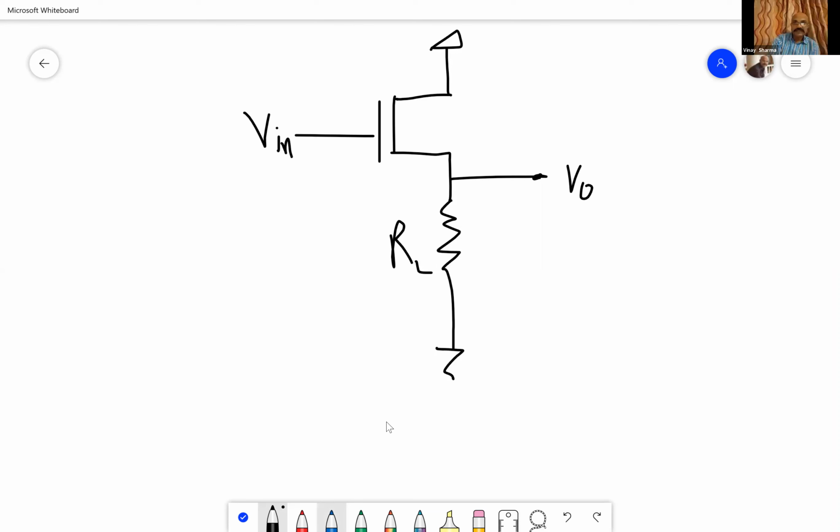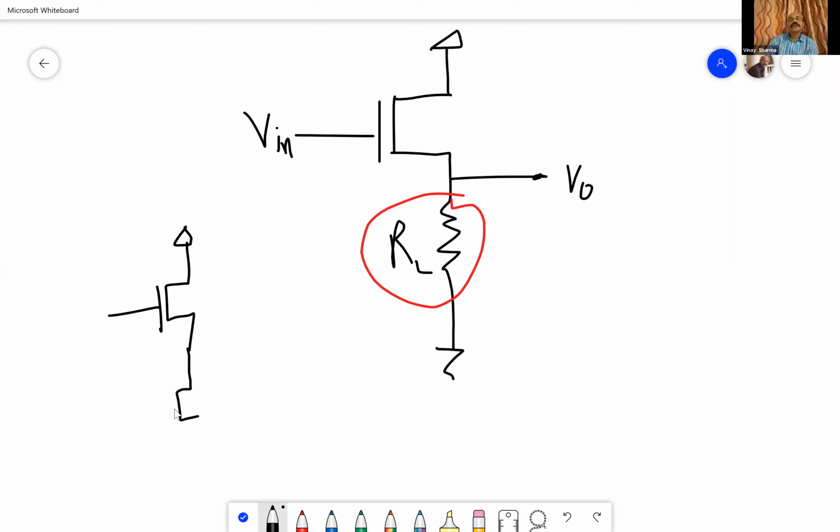Now here, instead of making a virtual resistance based resistor, what we will do is make an MOS and drive it through a VDD, and we will make another MOS that will have this value connected over here, and here the length would be very large.